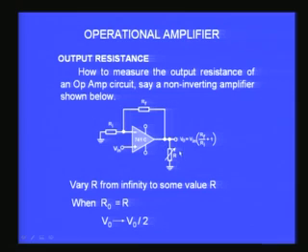Now, what I do is I connect a resistance between the output terminal and the ground, that is what I call R, and the arrow shows that it is a variable resistance. That means, the value of this resistance can be varied from some 0 value to some maximum value. Initially I disconnect this resistance, that means I make this R infinity. When I disconnect this, it becomes infinite resistance, and now I measure what is the output voltage.